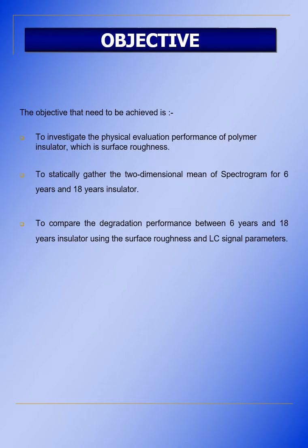Then, the objectives of this research project are, first, to investigate the physical evaluation performance of polymer insulator, which is surface roughness. Second, to statistically gather the two-dimensional mean of the spectrogram for 6-year and 80-year insulators. And the third is to compare the degradation performance between 6-year and 80-year insulators using the surface roughness and leakage current parameters.